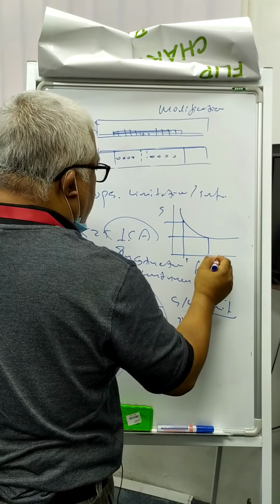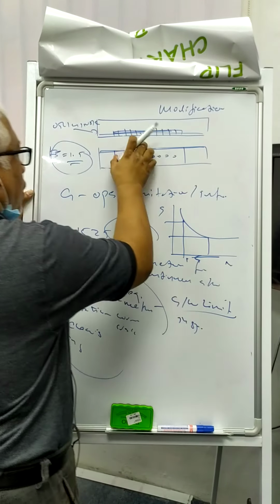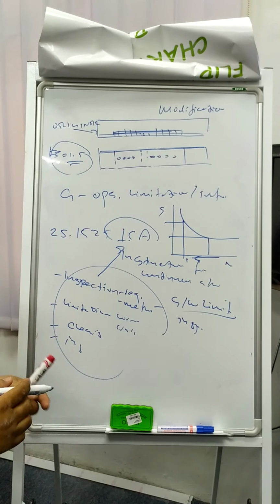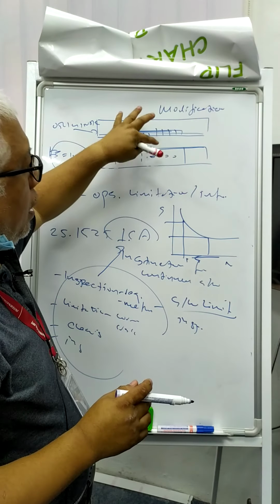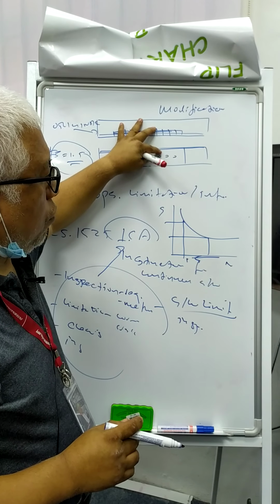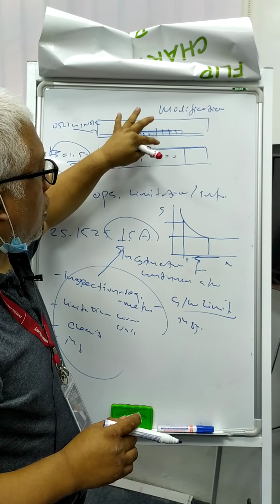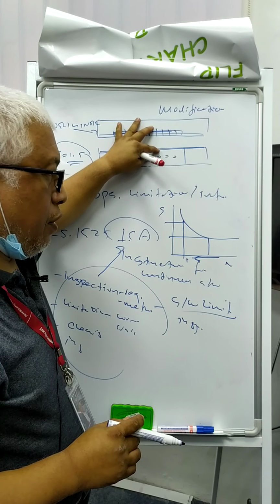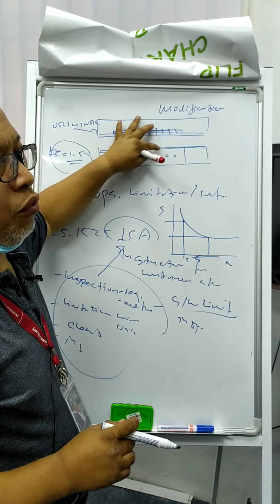So with increased stress, you can see the life is reduced. So you have to determine what the inspection requirement will be, because that area is no longer able to operate without any limitation, because you have already put stress here.